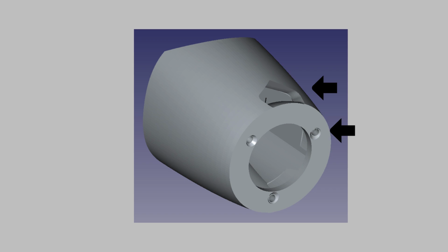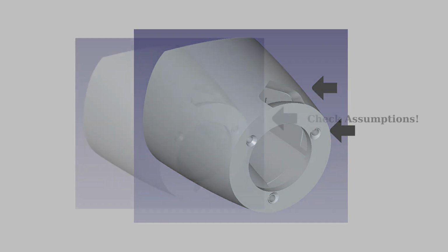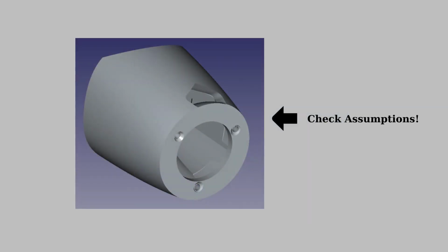Can it be done without compromising the structure of the fuselage? Looking at the STL, there are some mounting holes and ventilation openings that should not be corrupted. Next thing is, what kind of assumptions are we making? Well, the front face is circular. I certainly hoped it would be possible to take a simple shape, like a revolve or a cone, and apply some boolean logic to arrive at a good fit with the spinner.